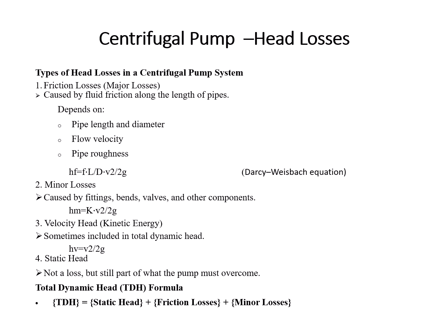We divide them into almost 4 types: major losses, minor losses, losses due to velocity head, static head. Static head itself is not a loss, but it is still part that the pump must overcome. Now, the major losses are mainly friction losses caused by the fluid friction along the length of the pipe.